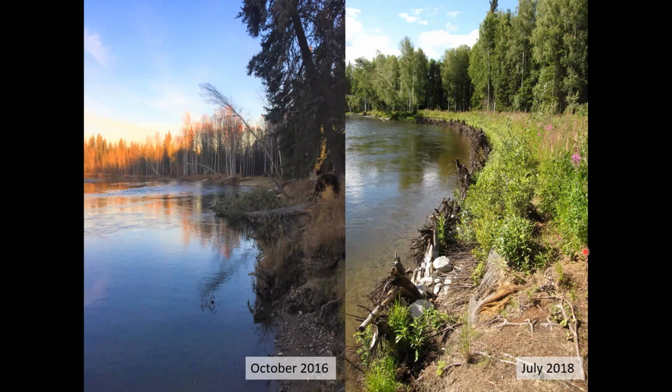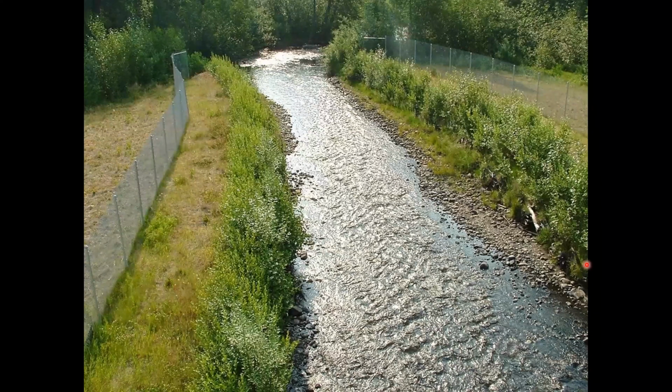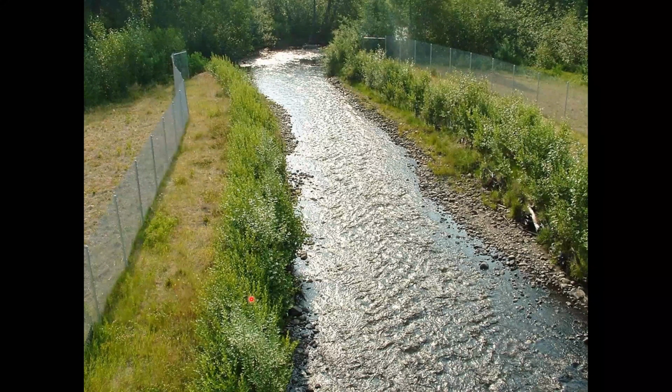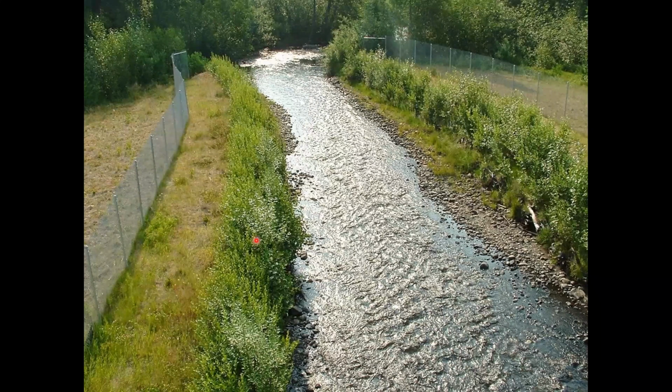Root wads have been used in many different areas. In this particular case, this is Fish Creek out in the Matsu Valley. From what I understand, prior to doing work, this was just kind of a muddy mess. We had ATVs going through, people walking through it. They wanted to put the channel back to where it needed to be and give it some constraints. So they put root wads in with a brush layer here. The point of the root wads was to prevent ATVs from going over and through the creek. They even took it a step further and put up fencing to really keep people and ATVs off the area.